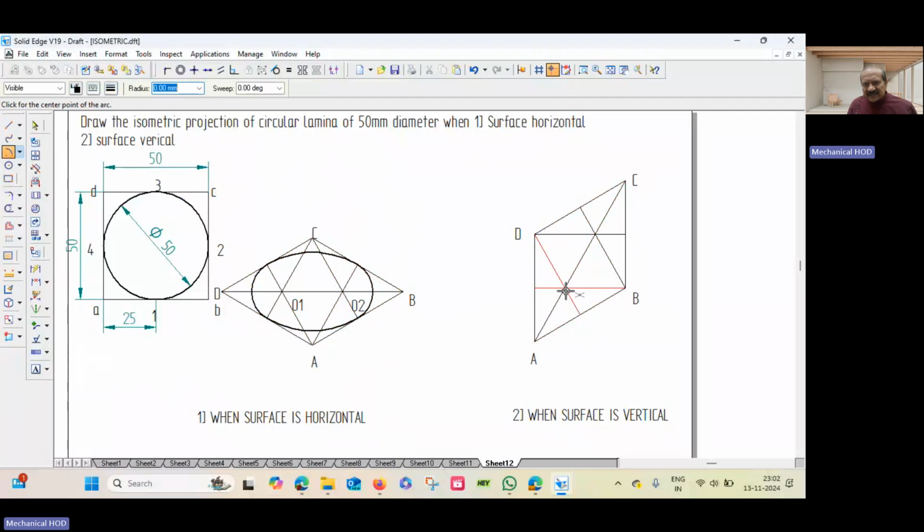This is the point of intersection of the three lines. Take that as the center. You can see the intersection symbol there. That is the center. This is the radius. You can see the endpoint symbol. Once you get the endpoint symbol, click. Then draw an arc. Similarly, come to this end, draw another arc. Then start from B. This has the radius. Draw another arc. Start from B.